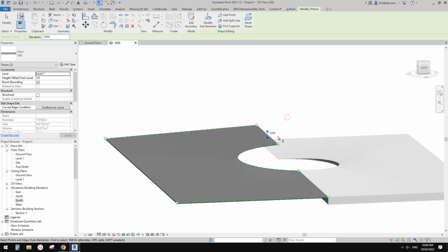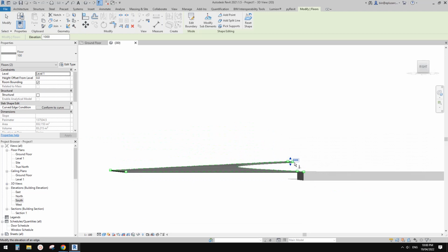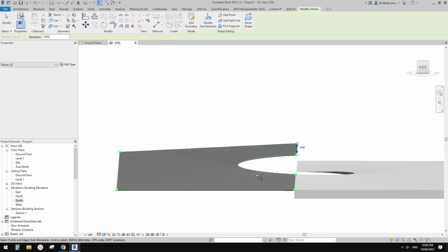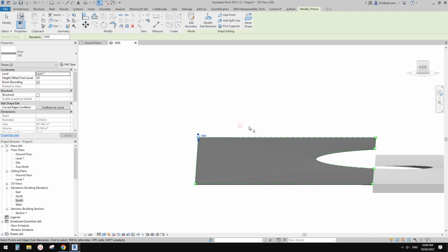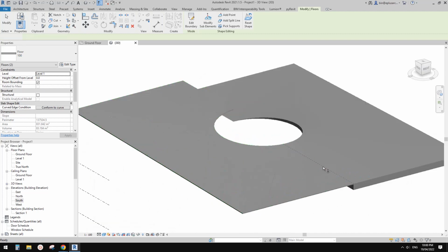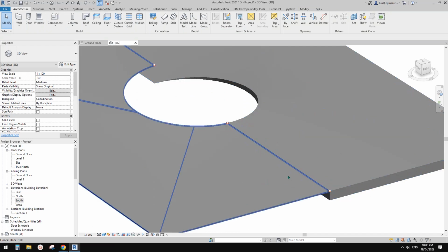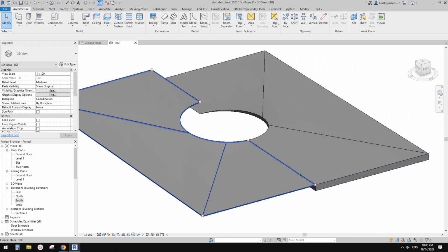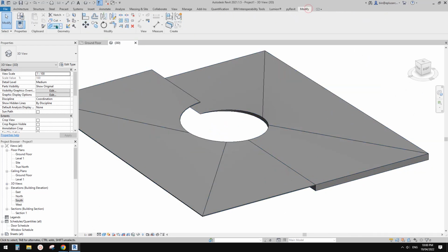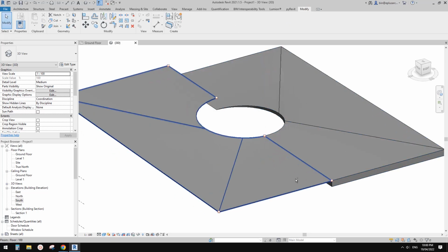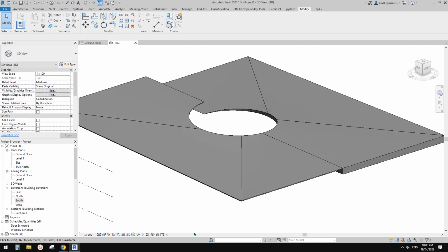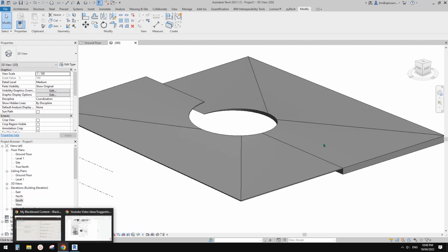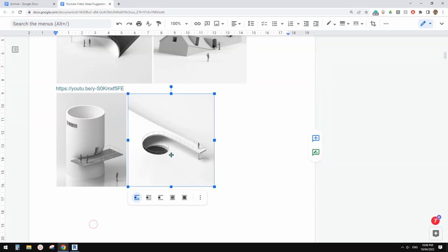So for example, 1 meter, it will go up to create a shape like a ramp, and then maybe this point needs to go up 1 meter as well. You will always see this line. You can join the floor, but you will always see these lines only when you are trying to render, and you can somehow adjust the lighting to make them look like one flat face.